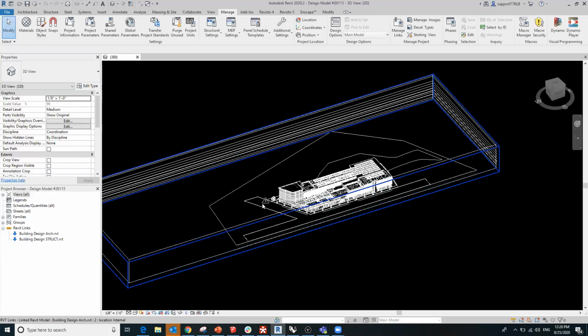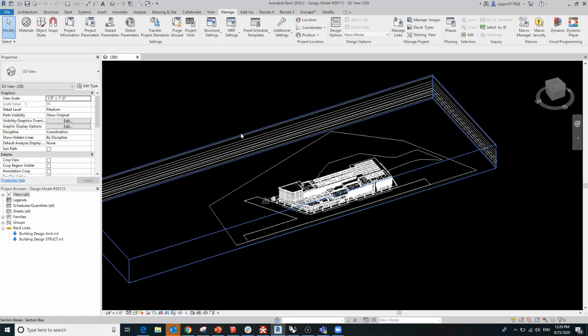When talking about Revit positioning, I won't go into too much detail here, I think we could do an entire webinar on Revit positioning itself. I do want to point out that when we're in a shared coordinate system, I want to align other models and export to Revizto using the shared coordinates option in positioning.